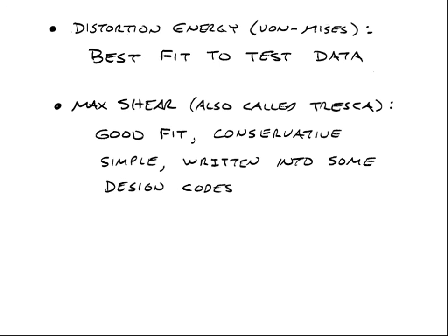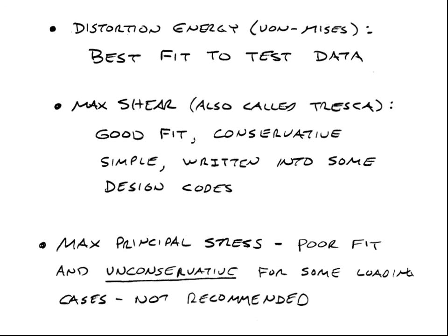And it's also, again, a pretty good fit, and it's conservative. Max principal stress, not only does it not fit well, it doesn't fit well the wrong way. That is, it's unconservative for some particular loading cases, and we don't recommend using that.